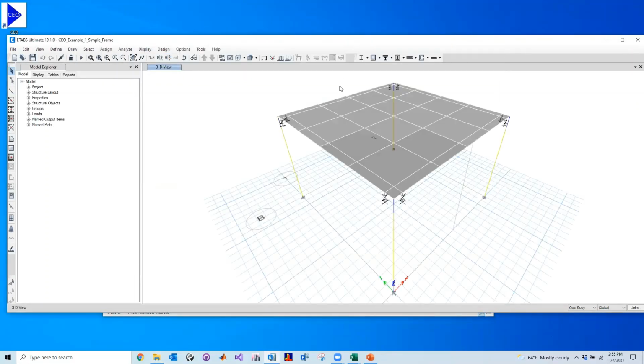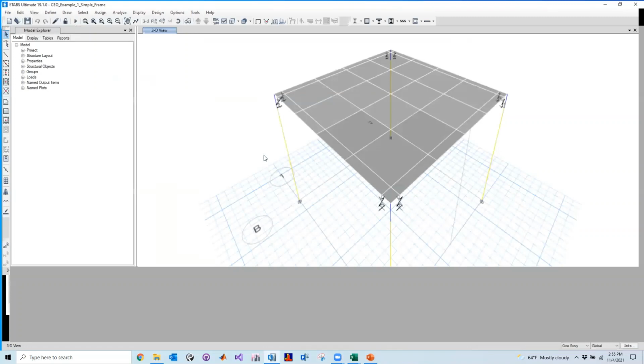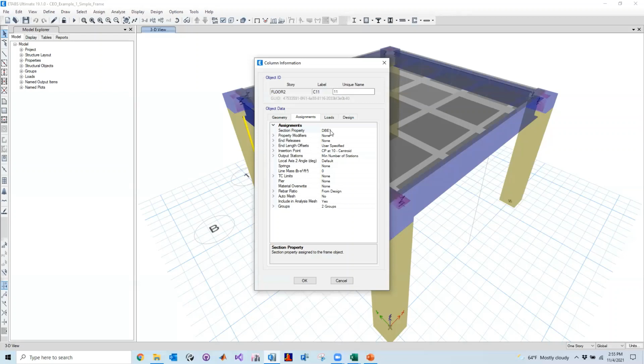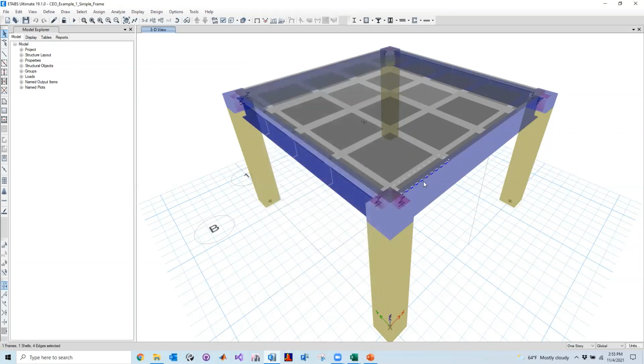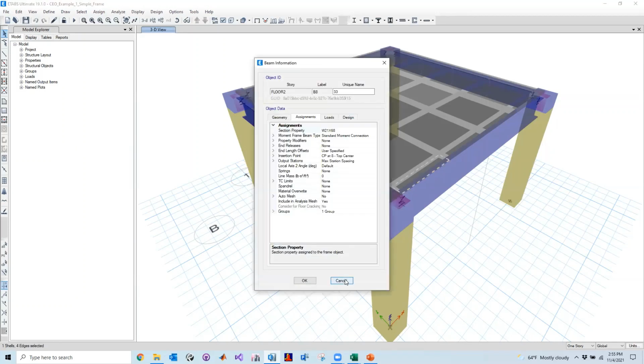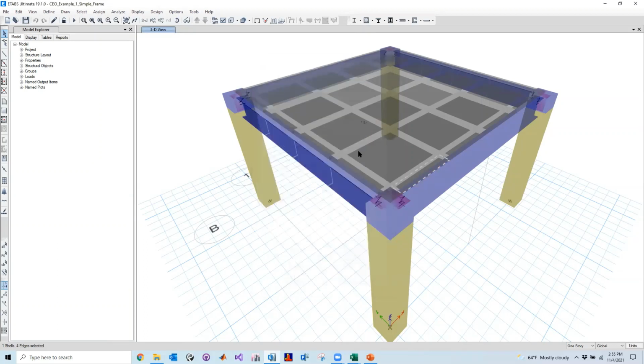So here's my ETABS model, and this is basically a screenshot we have over there. These elements over here are this DBE1. So these are displacement-based elements, right? Those would be the nonlinear fiber. The beams are W21x68. It's kind of randomly selected. Those are all beams. So that's a database section, defined in the database from the AISC sections.